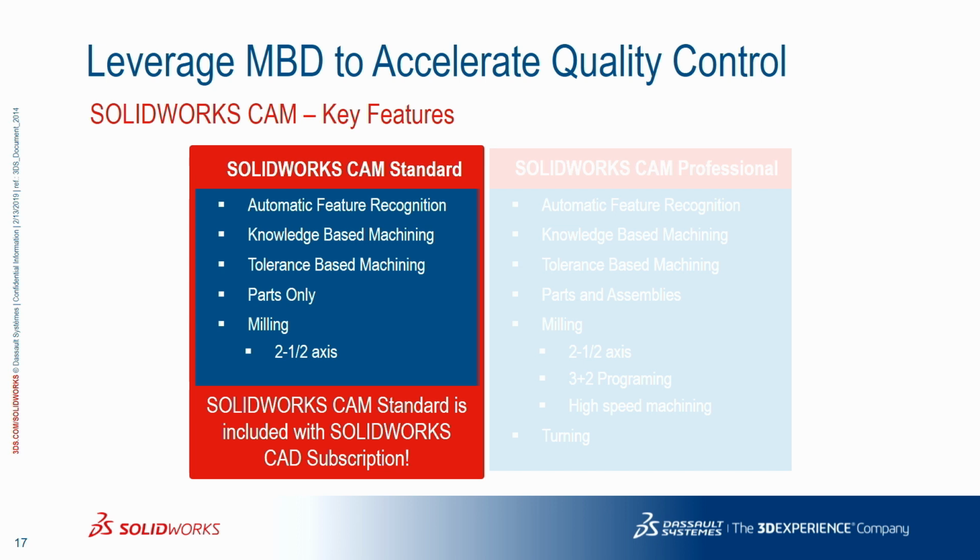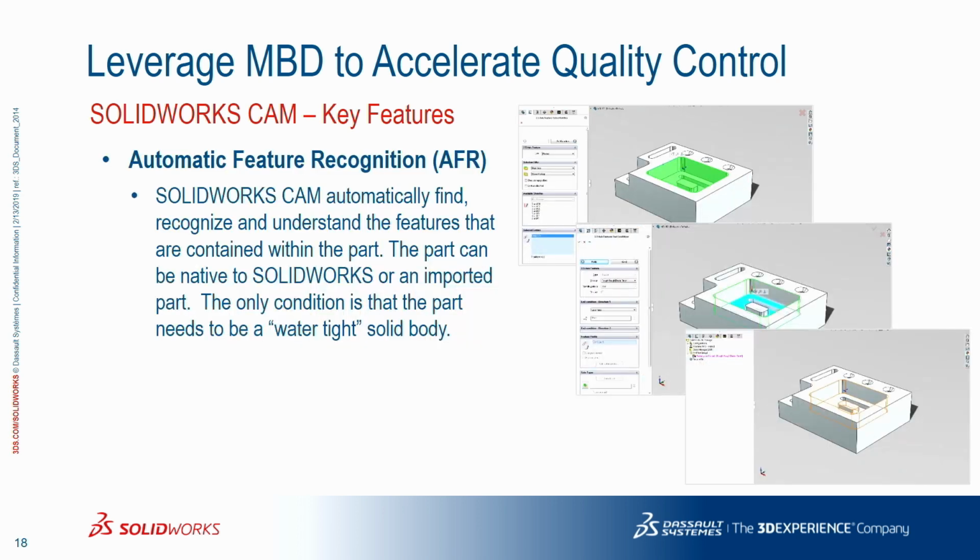The whole point of this solution is, again, to leverage your existing 3D data to expedite and streamline CNC machining. And just to show you a quick video, but before that, I'll point out a few things that are pretty unique to SolidWorks CAM. Feature recognition: because it's inside SolidWorks, it will recognize the different features, and based on the template you create, it will put in place some manufacturing strategy.